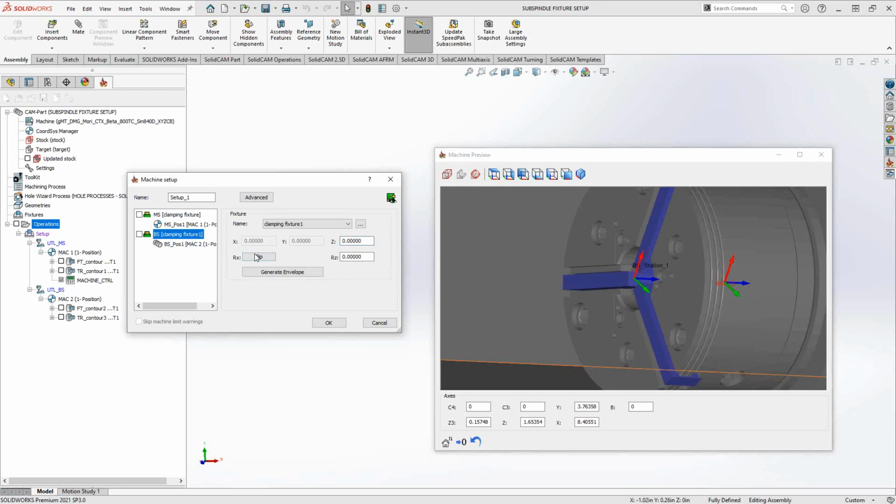But you'll also notice that down here we have this flip button. Now the flip button is actually just a simplification of the advanced mode here, where you could put not only shifts in the XYZ direction, but rotations around those directions. The reason we just have the flip button is because we just need to tell it that these jaws are facing the opposite direction. And that would be just a 180 rotation around X. So that's why instead of just putting a number, we just say flip.